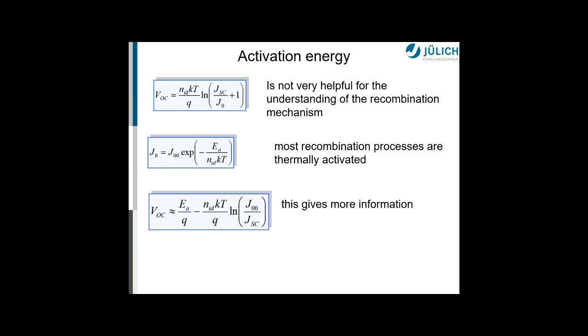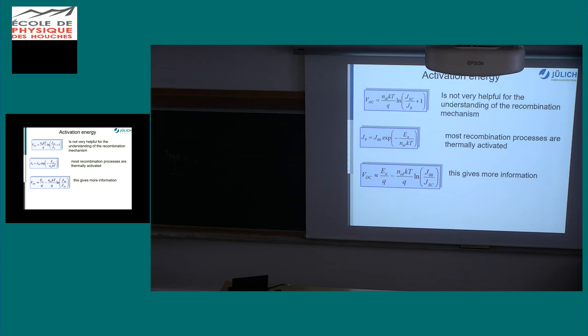And the activation energy is important, because if the activation energy is the band gap energy, you note that the critical point is still somehow in your absorber. So the interfaces are doing reasonably well. Only if your activation energy is getting smaller than the band gap energy, then you say, okay, that cannot be my bulk, that must be an interface, very roughly.